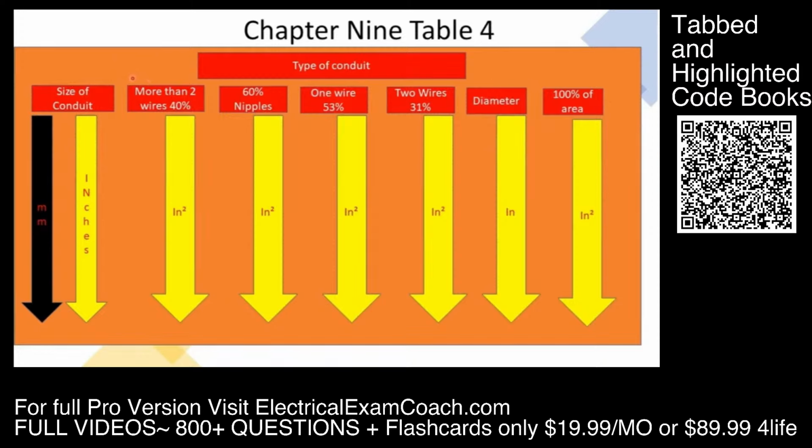The first one that we come to is when we have more than 2 wires. Anytime we have 3 or more wires, we're going to use this percentage. It's the 40% fill column. What it's saying is you're allowed to fill that conduit up to 40% of its capacity. And the values listed down below let you know what that capacity is. So we'd start here on the left-hand side, find our size of conduit, and then come over to our respective column, and that lets us know the total square inch capacity of this pipe that we are allowed to fill. In box fill, we use cubic inches, but in pipe fill, we're going to use square inches.